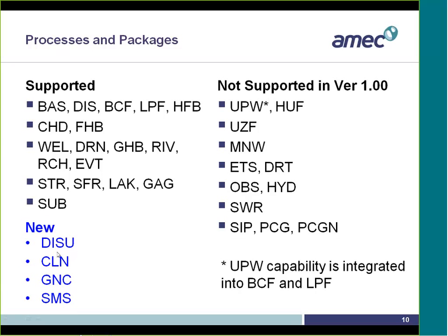Additional packages are a discretization package for unstructured grids. MODFLOW-USG is first of all fully backward compatible. You can use it with structured grids, we'll talk about that later, as well as unstructured grids. So if you have structured discretization, it uses the original discretization, but you have a separate unstructured grid discretization.